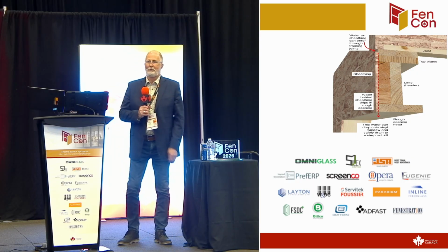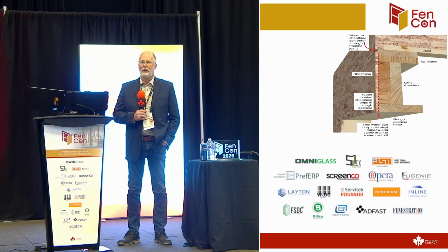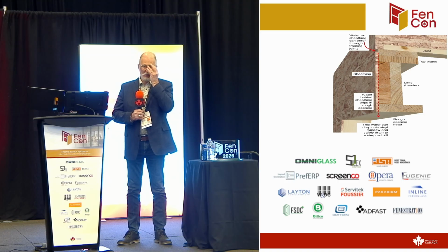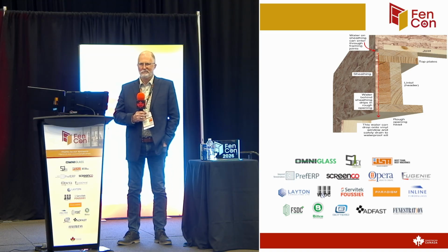Right. I guess there's always those offsets where you're getting the benefit of that rain screen principle. You're presuming failure. At one point, you're getting water to shed out if it gets in. But then the offset of that is, are you then allowing air? Like for Winnipeg especially, we have cold climate, very cold air. You're allowing that air and cold weather to essentially get closer.